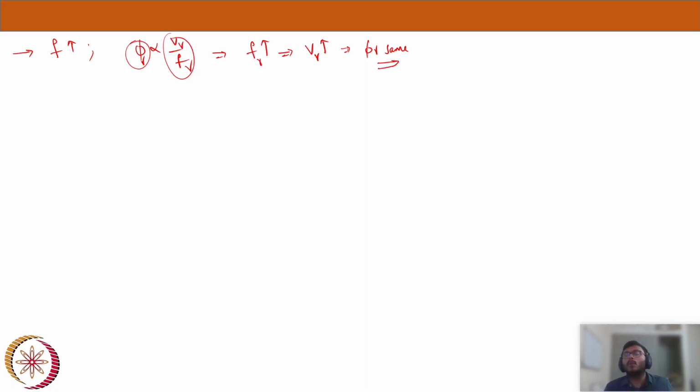details. If my motor is a 400 volts rated motor, never go beyond 400 volts, because my motor windings are designed for that particular voltage. If you go beyond the rated voltage, the insulation might not be compatible. Insulation is provided for rated ratings.